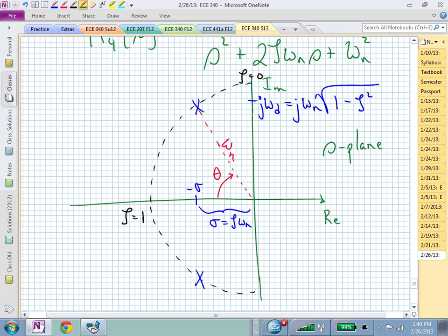And then you would just go unbounded. If you have poles on the imaginary axis, now if you excite those at that frequency, you're going to have an unbounded response as a function of time. That's all I'm saying.